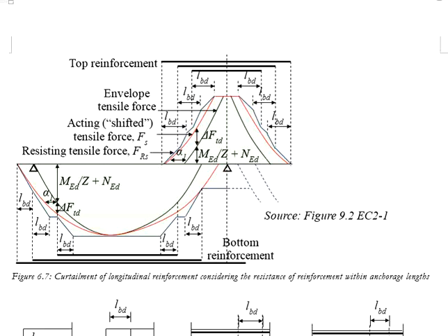Let's say a beam is lightly loaded, where 2 units of H12 rebar is sufficient to withstand the moment and tensile force here. And you know that for a typical beam, industrial practice will have a minimum of 2 H12 rebar. That means there is no point for you to do the curtailment. You cannot reduce the reinforcement further.